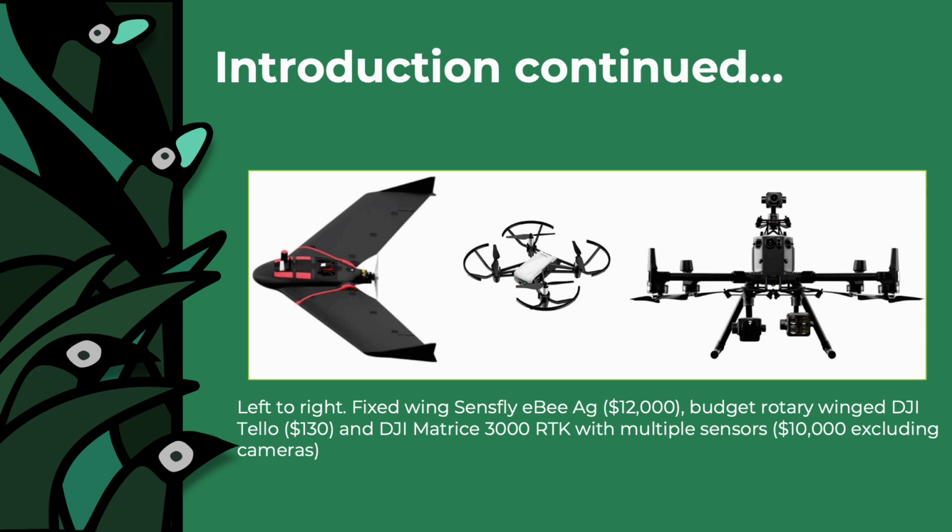The GCP coordinates are used to refine the positions of the photogrammetric output. In some circumstances, this will render results to accuracy within a few centimeters. This high level of precision and accuracy may be important when attempting to integrate diverse, spatially registered data within GIS software.